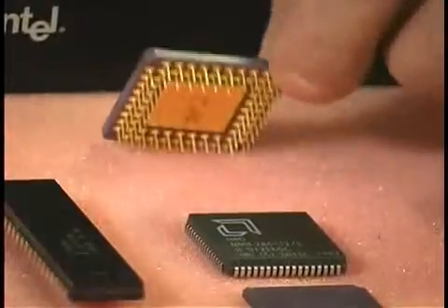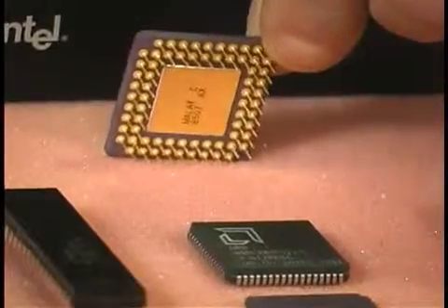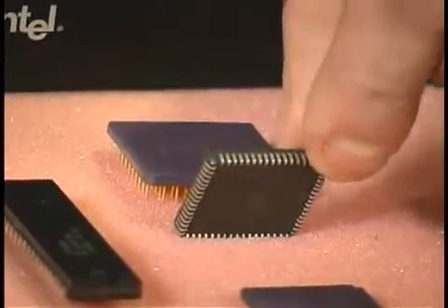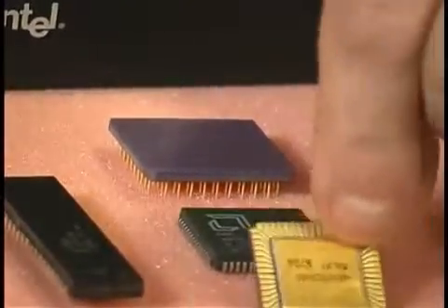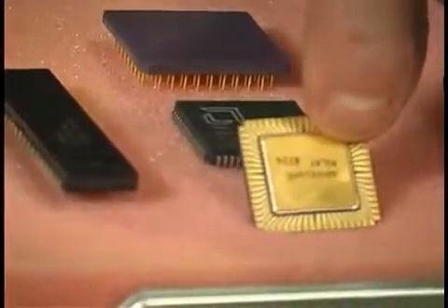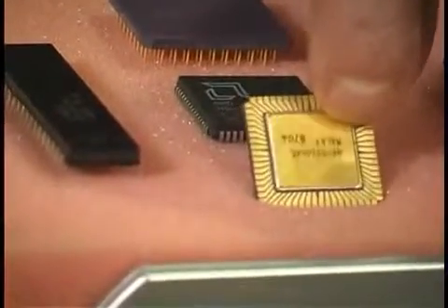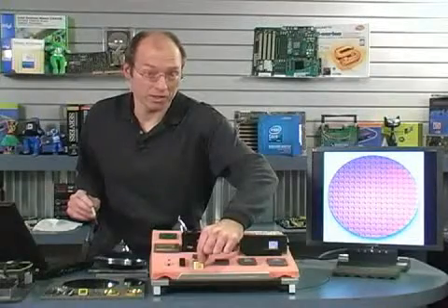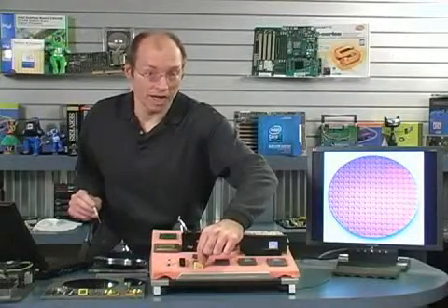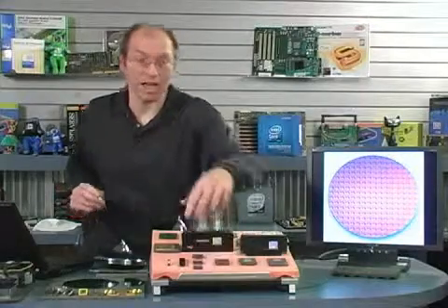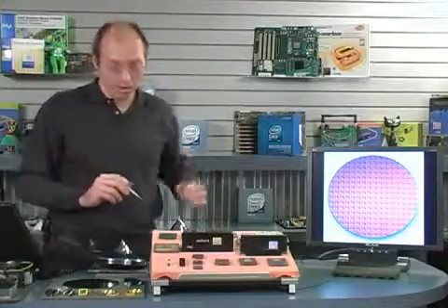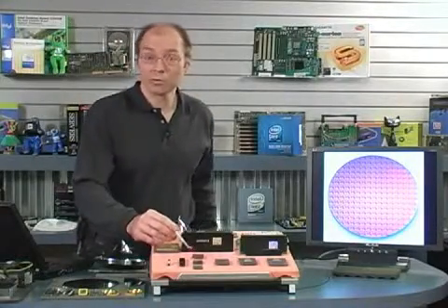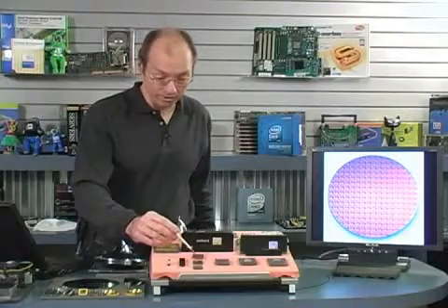This first one uses pins that plug into a socket. This is a different design which uses pins around the edge of the chip. And then this one had no pins. The pins were actually in the socket on the motherboard, and there were just lands around the chip. Now, what's interesting is that just in the last few years, this type of packaging has returned, and most of Intel's processors now use this land grid array, they call it. So at this point, processing speeds went up to about 10 to 20 megahertz.